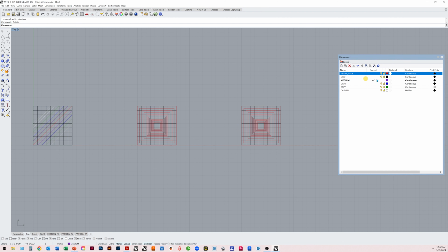Watch. If I could use that trim command, I could come in here, use that as cutting objects, and then start to get rid of anything that's in between here and here. Now look how I'm going right to left and just selecting those surfaces. Look at that. Now let's try that again. Let's use the trim again.